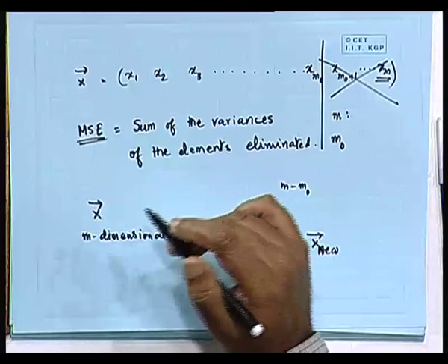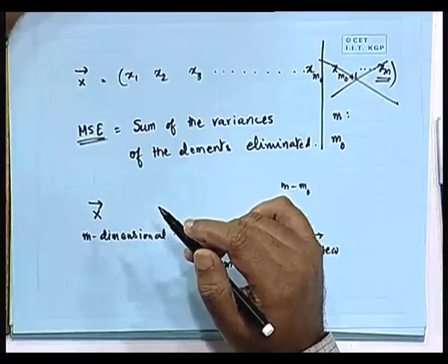One of the things which all of you must have done is the use of orthogonal transforms, which serve as the basis functions, and we can reconstruct a signal on the basis of using those orthogonal functions. We know about the Fourier transform, we know about the cosine transforms and its discrete versions in the form of discrete Fourier transform, discrete cosine transform, etc. All these things are giving us this T matrix in some form. It is based on some definite kernels which exist.